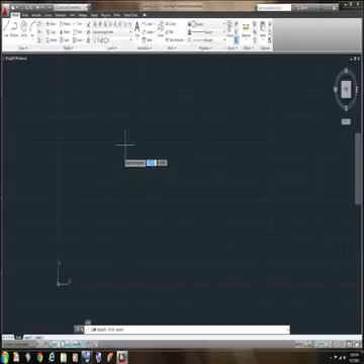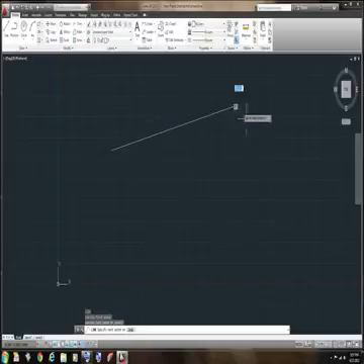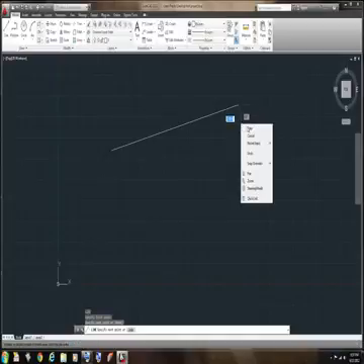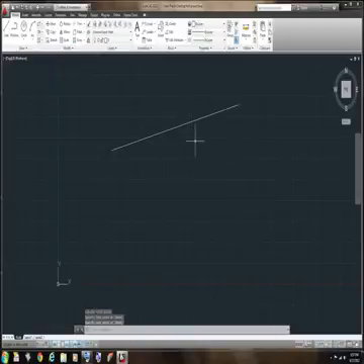So you have several ways to do the same thing. You can go ahead and click line here, or you can type a shortcut on your keyboard, L, enter, and now it's the same thing. You can look at the command line, and it's saying to you now specify next point. You see, and we're doing the same thing. You right click after you complete your line, you hit enter, and your line is done there.